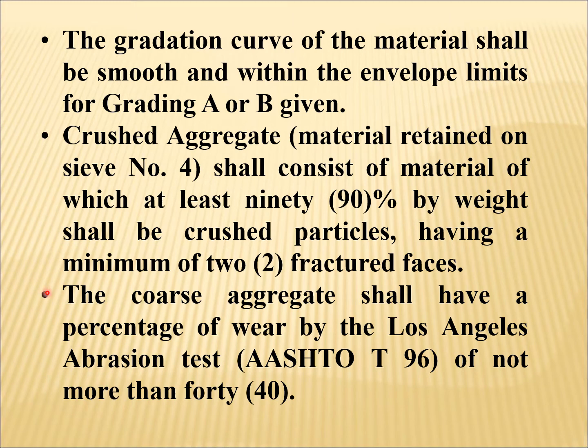The coarse aggregate shall have a percentage of wear by the Los Angeles abrasion test of not more than 40. So you can see here we are having a strict criteria that the Los Angeles abrasion test value should not be more than 40 in the case of base course material.